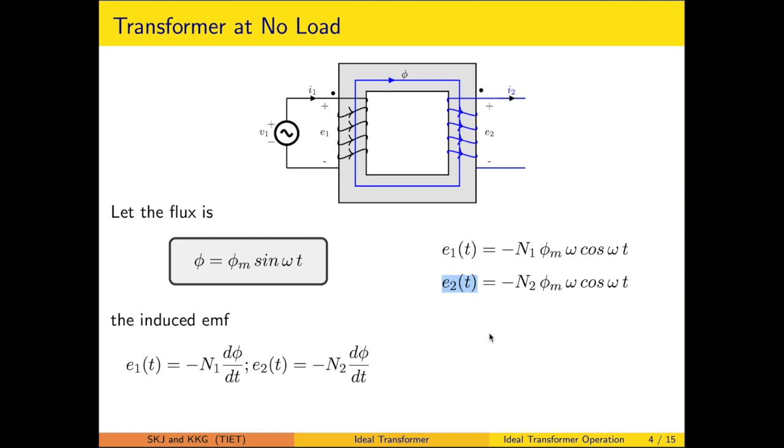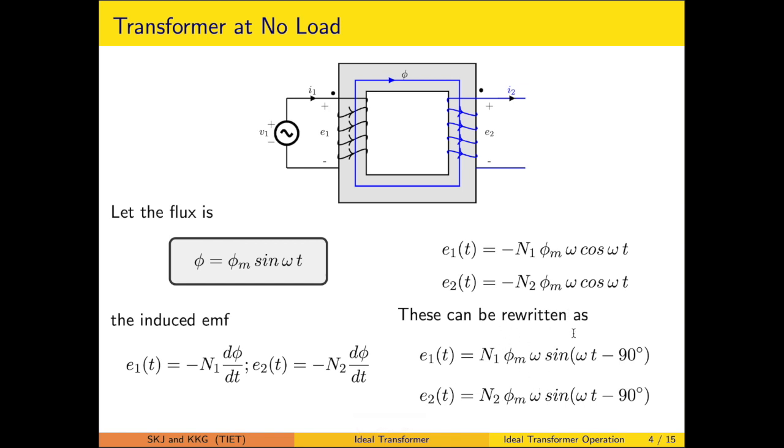Then we have to have a phasor analysis. So we will be writing these two terms suitable for the phasor analysis. The only difference carried out here is that the cosine term is represented as sine, because the sinusoid was our reference phasor for the flux. Another important aspect is that we will be writing this into the standard form of omega t plus or minus theta degrees. So it is to be written accordingly.